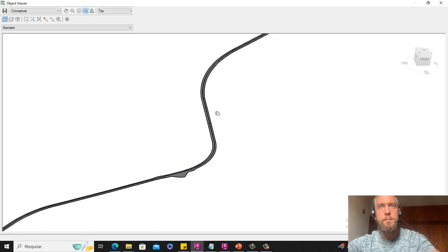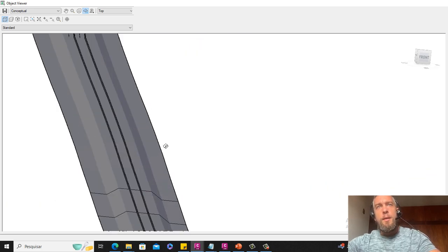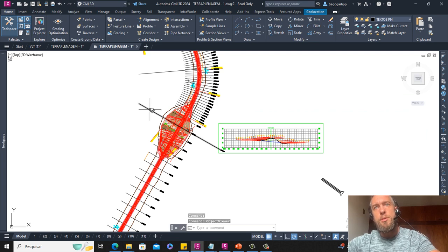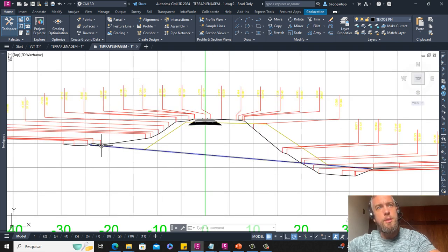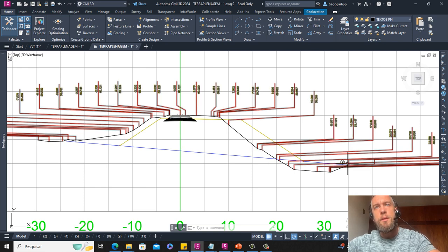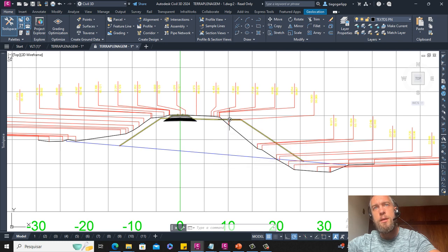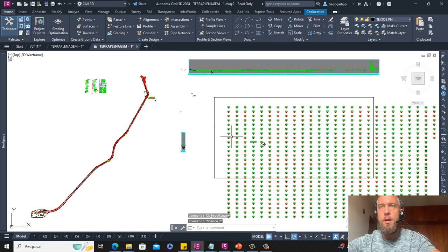As you can see, the track and so on. And at a specific station we have a complex situation, because we needed to consider this subassembly to create the excavation for this topography, the existing ground, and afterwards, in a future step, to create the embankment reaching this last level of the surface.